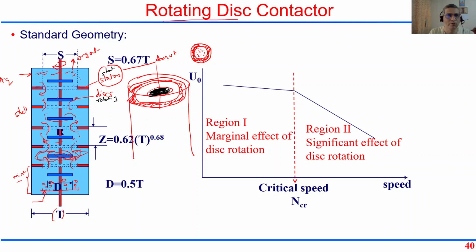It flows through this gap. Now you see this gap has to do two things. One thing that these stators, or these donuts, have to do is prevent axial mixing. That's how they are blocking. They are physically blocking part of the flow. And in whatever opening exists in that washer, in that donut, if you look at the top view of the donut, the droplets are coming upwards in this gap, and the aqueous phase is going downwards. You see, the droplets come up and the aqueous phase comes down through this gap, right?